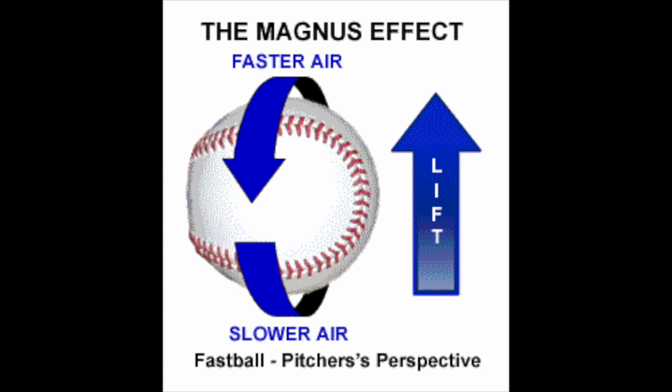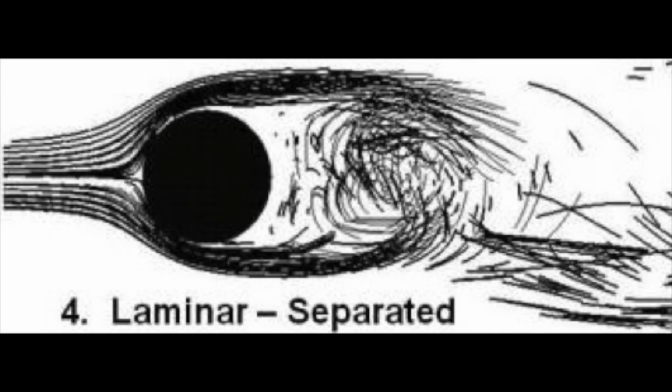If the wind tunnel is running at about 25 meters per second, the baseball would have a Reynolds number of about 1.4 times 10 to the fifth compared to the cylinder at about 3.14 times 10 to the fifth. Its low Reynolds number indicates that the baseball would experience laminar flow. It's preferred to have the baseball experience laminar flow because pitchers need to have a clear understanding of how the ball would react with different pitches. If it would experience turbulent flow, then the pitches would be unpredictable, negatively affecting the pitcher's team. The picture below is a good demonstration of what occurs with a baseball.